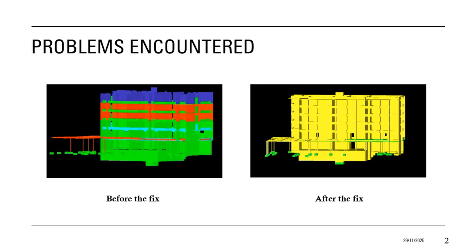This color persistence creates a conflict. When the simulation progresses to the formwork removal task, the yellow color assigned to this activity fails to be applied effectively because the structural elements are still visually blocked by the red and green color layers of the immediately preceding task.